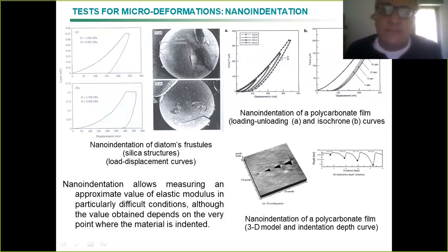In other cases, if you have a little bit of viscous behavior, that means that you need to be aware that you have different behavior, whether you pull it fast, say 100 millimeters per minute. That's what usually you do on a tensile test. You set your tensile testing machine to a velocity of pulling. For example, you say 1 millimeter per minute, 10 millimeters per minute, 100 millimeters per minute. And it makes a difference. If the material was completely elastic, it wouldn't make any difference.